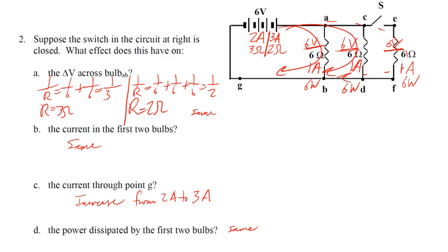When you had your voltage, you knew that there was 3 ohms of resistance, and you found the current was 2 amps. And that's fine. Then you were able to use those 2 amps and identify that they split into 1 amp for each of those 2 resistors, and they both had 6 volts. Each one ends up with 6 watts of power, and that's fine.